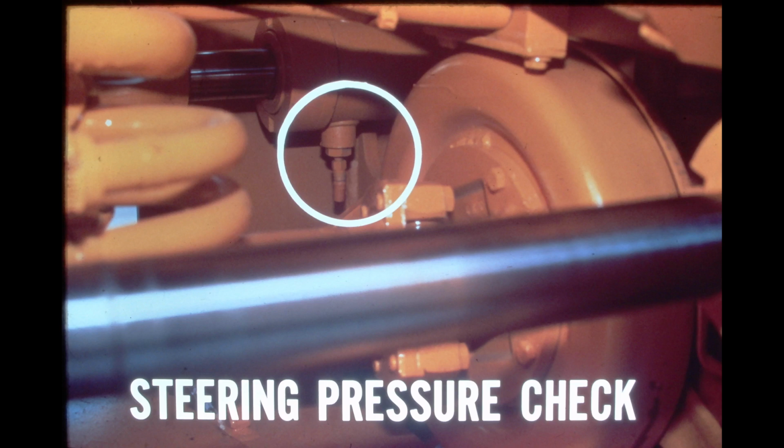A quick disconnect for checking pressure is provided on both of the steering cylinders at the rod end. To check this pressure, install a gauge with a hose long enough to allow you to stand away from the machine. Lock the frame halves together and turn the steering wheel. If you are checking the right cylinder, turn the wheel to the right. For the left cylinder, turn the wheel to the left. Check the pressure at low idle and at high idle.